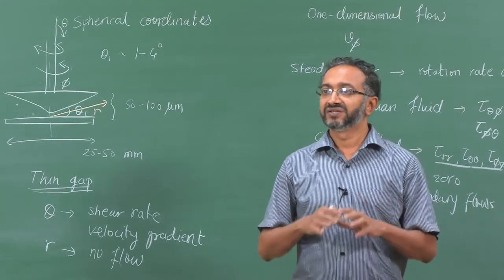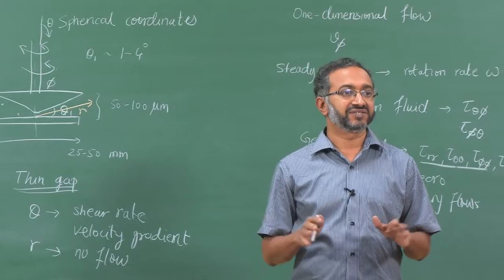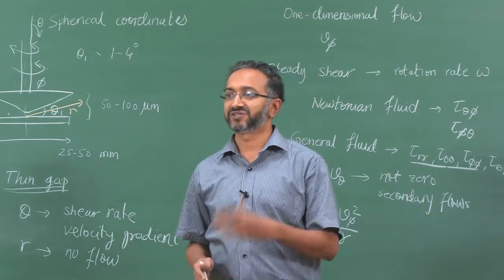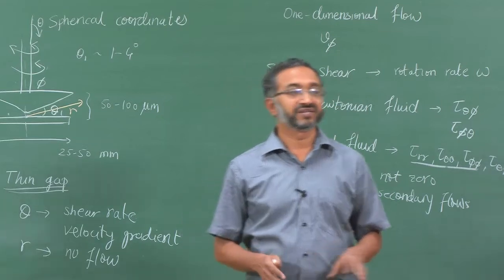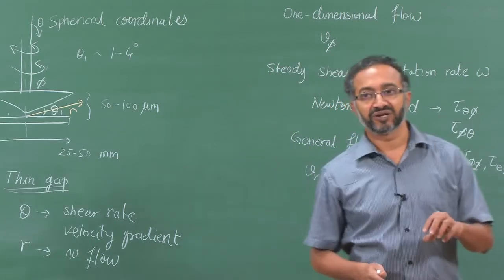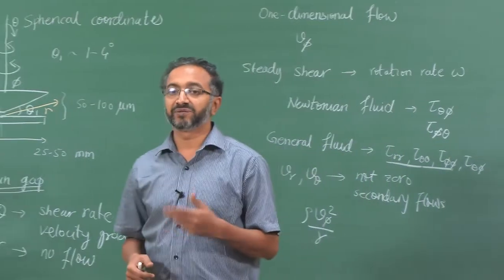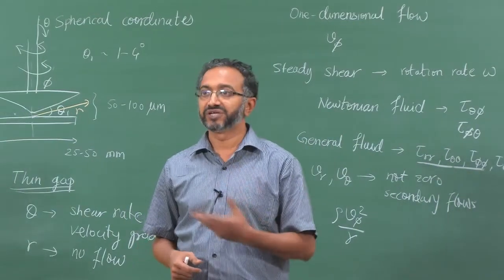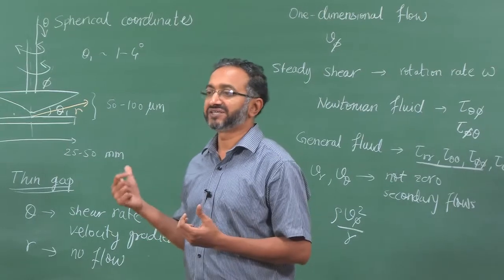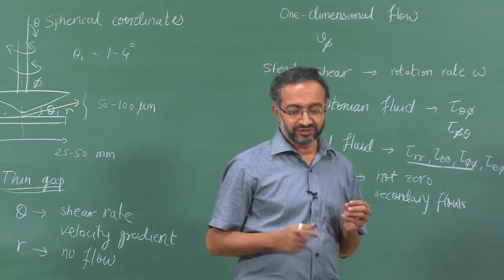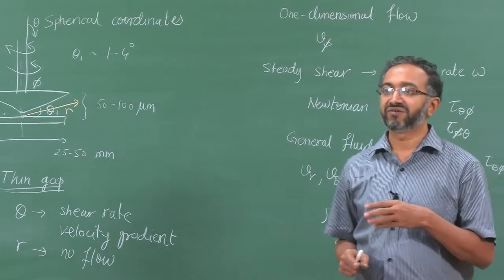In industrial pipeline flow, we learn that at a Reynolds number of about 2100 or 2300 we assume turbulence. But in micro channels, even at lower Reynolds number, turbulence can develop. So, depending on the disturbances developed due to the rotation or oscillation in the geometry, you can have local pockets of turbulence. Therefore, in all these cases secondary flows are possible.